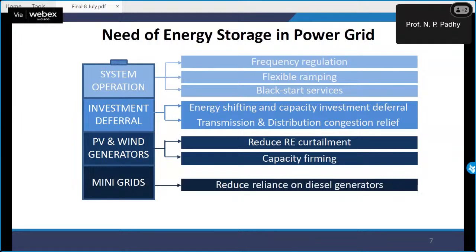In that case, I can have some local generation to cater so that the load beyond my substation is not going to increase. So whenever there is an opportunity, I'll keep some energy available, so that the peak 1 hour that the substation is going to face can be avoided by discharging these batteries.